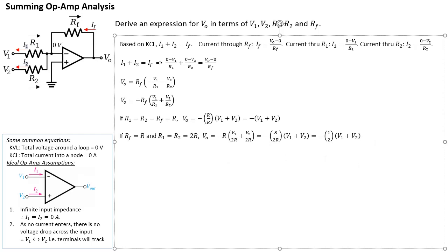All right, so if you have more than 2 resistors here, if you keep on adding, you know, 1, 2, 3, 4, 5, and so on, and then for those values you make it to be n times R, if there are n resistors, n times R, then you can create an averaging circuit. So this is an averaging circuit, right? The output voltage will be the average of the 2 inputs. So this is another interesting equation or setup that you can have.